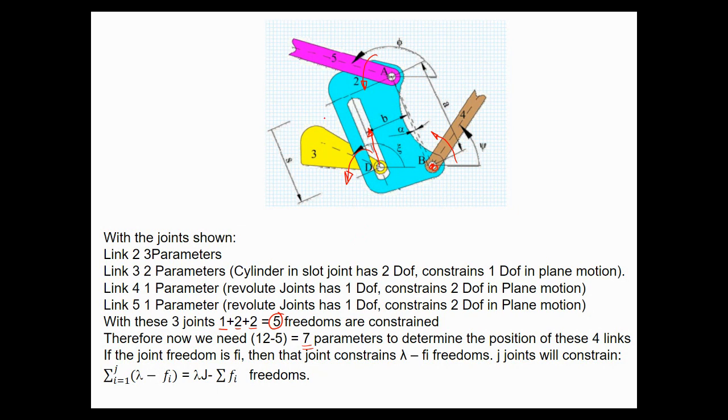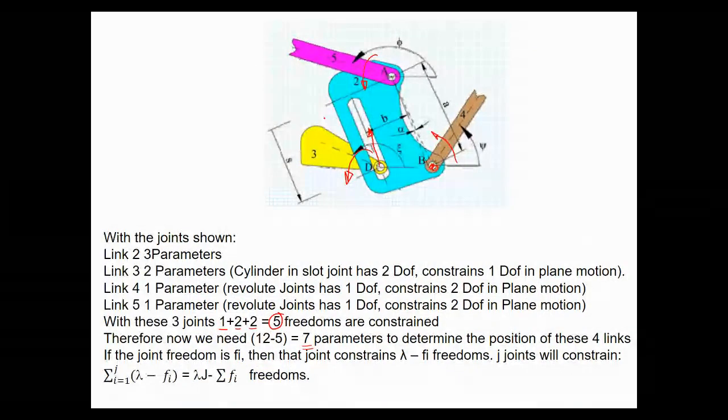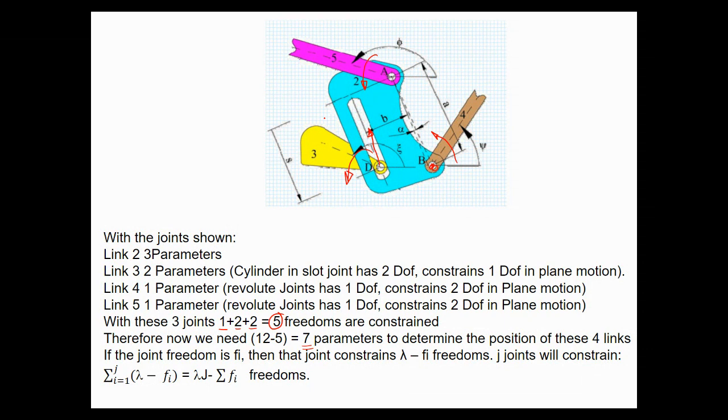Is this understood? Is this clear? May you explain it again? Okay. The 3 joints. You have 12 degrees of freedom when they are totally unconnected. Right? This picture you understand. There are 12 degrees of freedom. And we decide to connect them to each other like this. One cylinder in the slot joint, here, between 2 and 3.